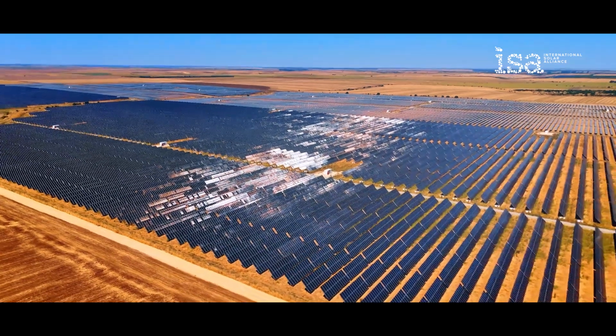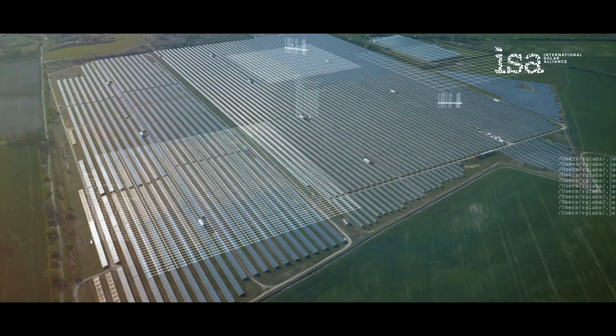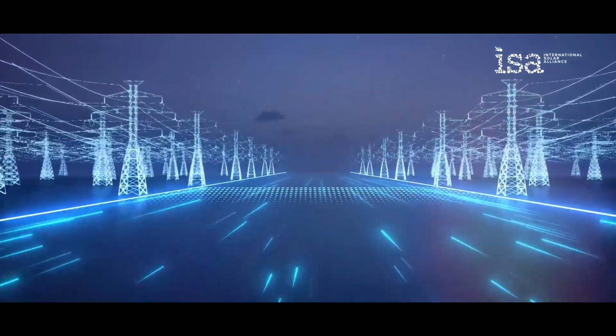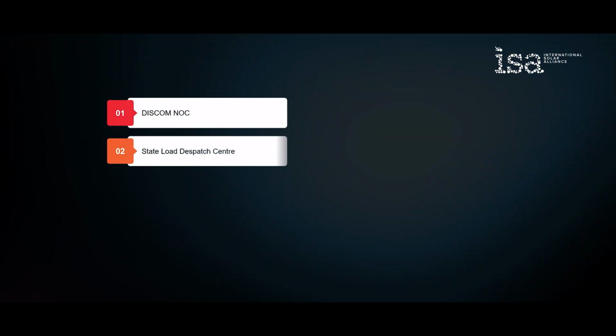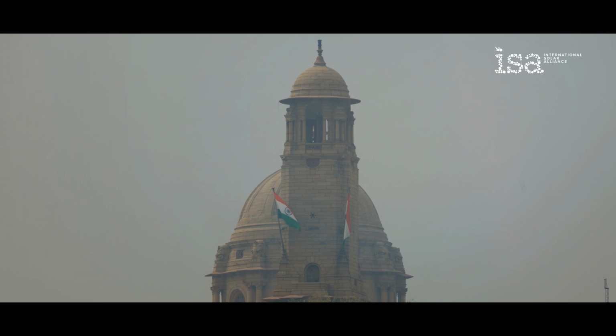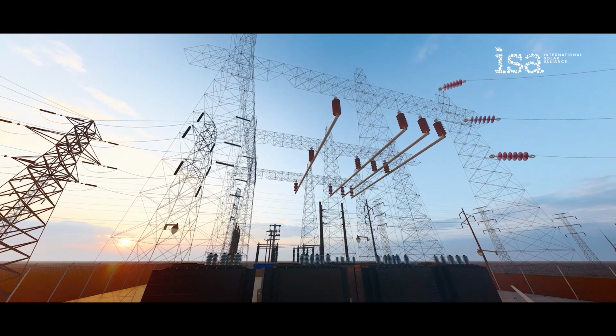Essential approvals for large-scale solar plant grid connectivity in India, for illustration, include the following. DISCOM NOC, a fundamental mandatory requirement to confirm the grid has the capacity to absorb the power generated. State Load Dispatch Center, required for synchronization with the grid and ensuring the plant complies with state-level solar policies and grid stability requirements, such as active power control and reactive power support.